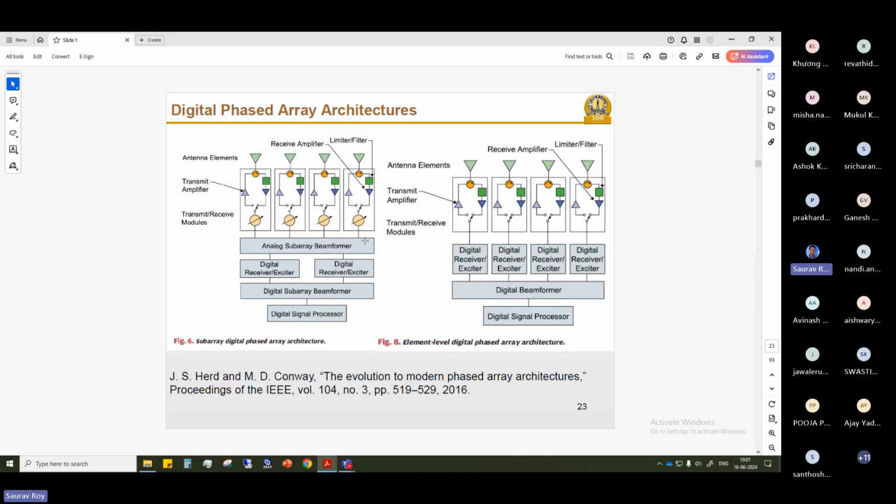Now, this is one part. You can use the individual antennas separately with multiple beamformers. That is one thing you can do. Another way, and there is a lot of research on this, is that you can divide the multiple antennas into sub arrays. You take two antennas as an array, and another two antennas as a defined array. These are called sub arrays inside a big array. By feeding them differently, intelligently, you can make a lot of different beams and a lot of intelligent operations. So there are a lot of options available there.